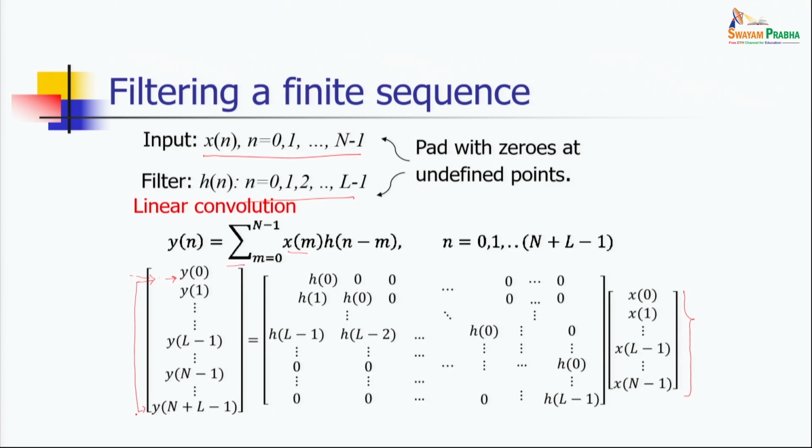After this length, after this capital N, the nth point of this sequence, you are padding with 0, so there is no excitation. So the response will be felt till the time point of n plus l minus 1. And you can see that this convolution sum, these product and sum operations, are expressed by the respective dot product of the rows and columns in this way.